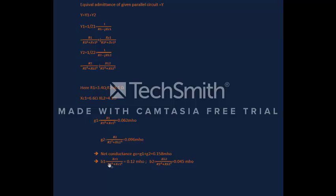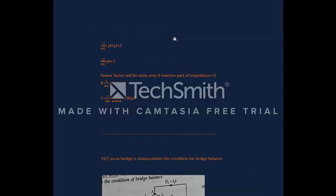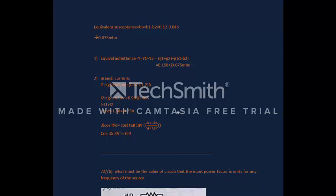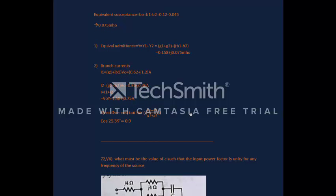In a similar way, we'll calculate B1 and B2. For B1 it's XC1 upon R1 square plus XC1 square. B1 turns out to be 0.12 mho, and B2 turns out to be 0.045 mho. The equivalent susceptance B0 is equal to B1 minus B2, as it lags, which is 0.12 minus 0.045, turns out to be 0.075 mho. Equivalent admittance Y is equal to Y1 plus Y2, which is equal to G1 plus G2 plus J(B1 minus B2) is equal to 0.158 plus J0.075 mho.